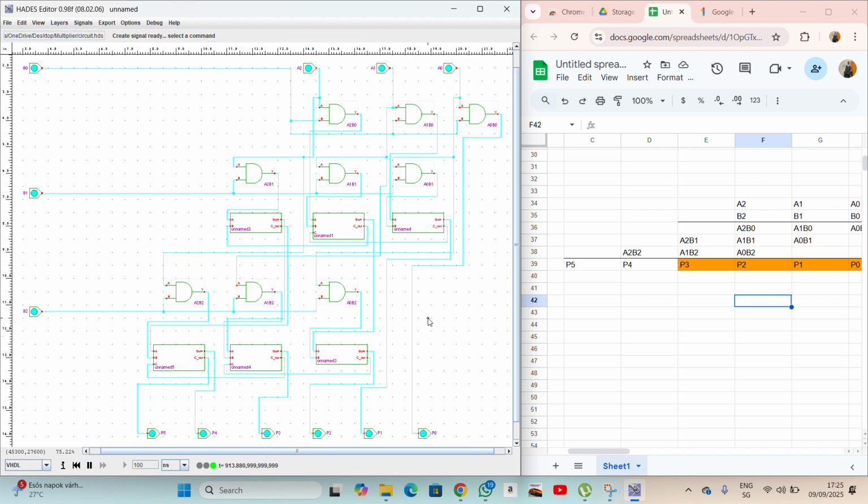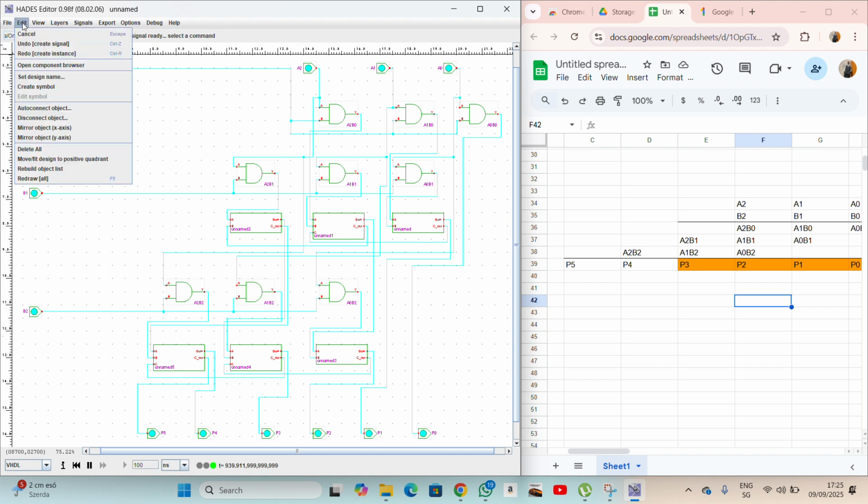So now this is the final design that we have, and whatever we are having here as a circuit is simply what we worked out on this other side. So now we have to create a very big sub-design for this, and that sub-design, we are going to represent it in our very final work. So I will have to create a symbol for this, so I will come to edit and create symbol. Then I'll have to save this, so Control+S, so everything has been saved again.